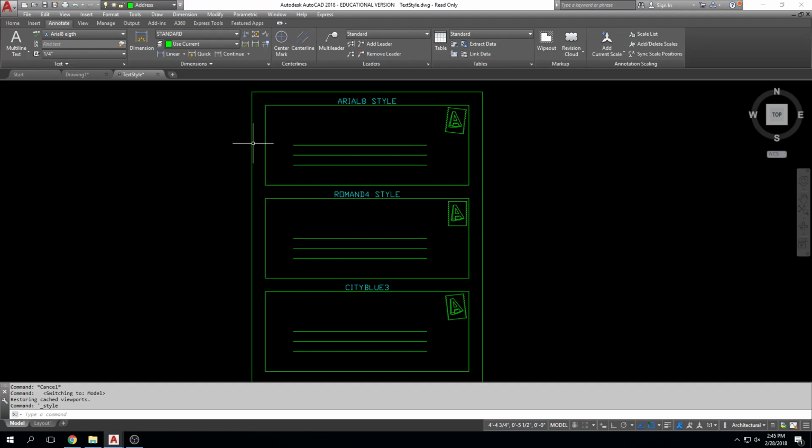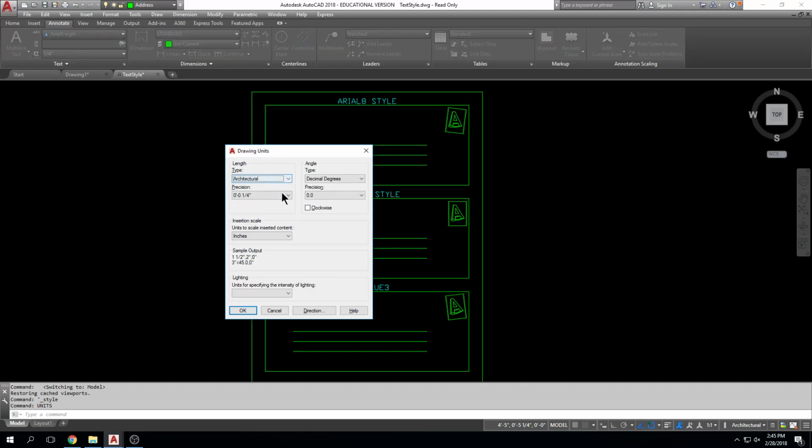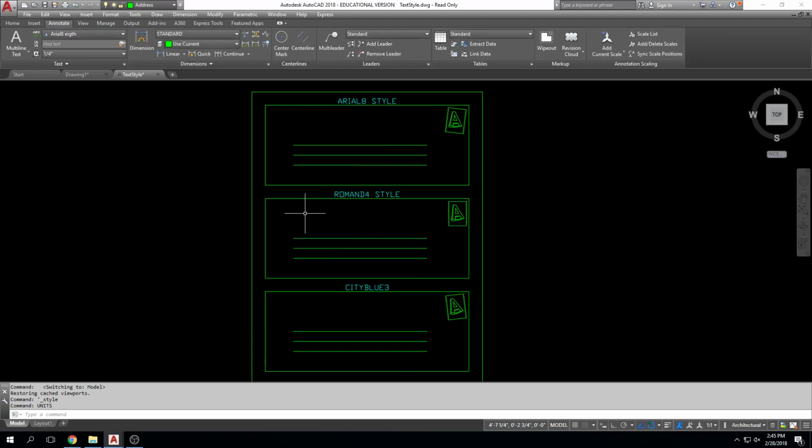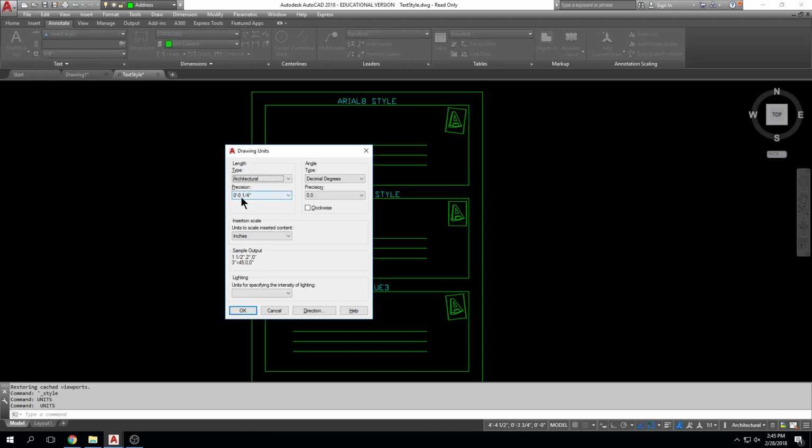All right, the reason that it's changing your font from an 1/8 to a quarter is because your precision is not set to a tolerance that will recognize that, likely, right? So if you go into units and hit enter, that's a really good illustration of why we changed the precision in AutoCAD, okay? Did mine change to a quarter? It did? I didn't even notice. I typed in an 1/8. So the reason that's happening is because under my units, I have a 1/4 of an inch set for precision, right?